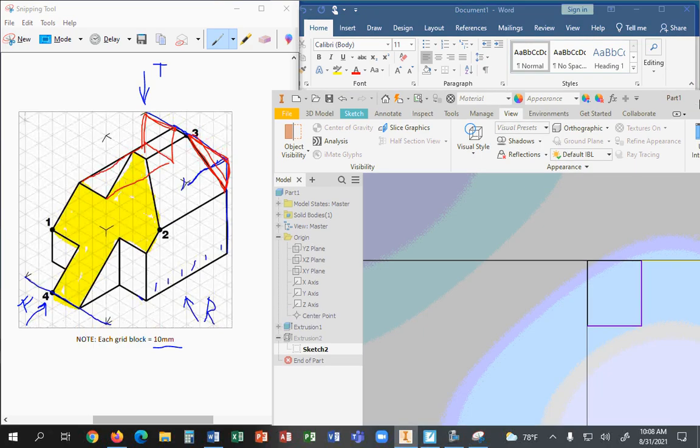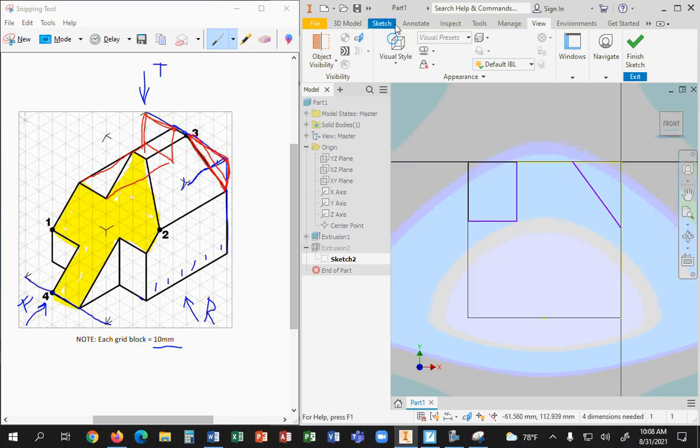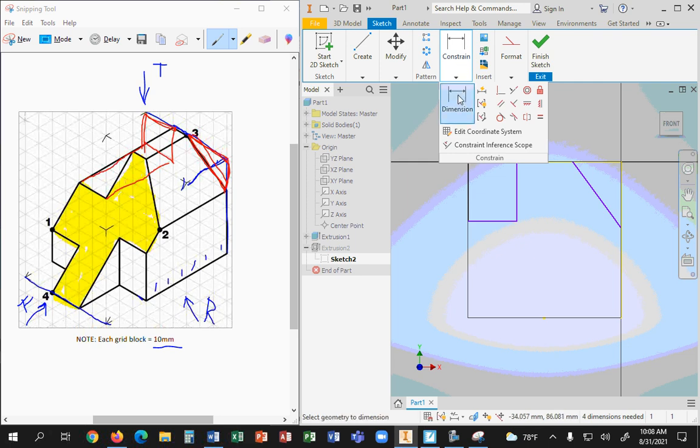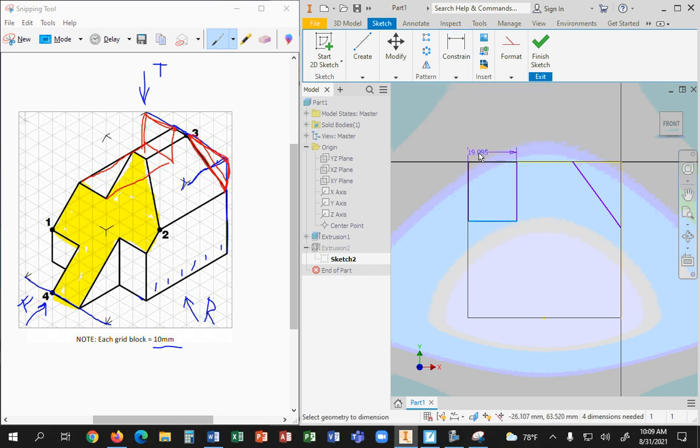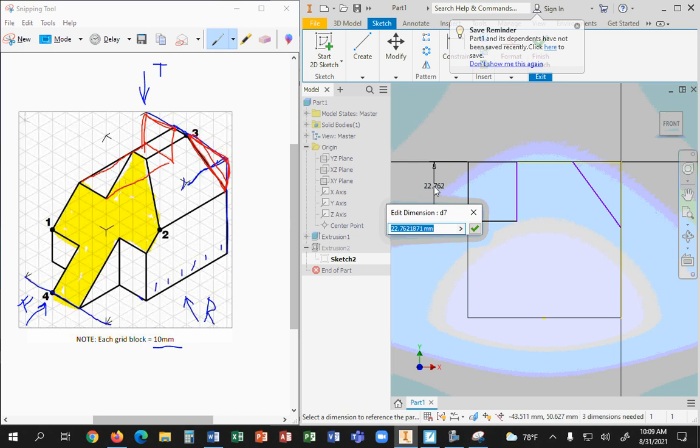Now in this view, I can go ahead and apply the dimensions I need to apply, the dimensional constraints that are important. Now notice I picked the midpoint. No, I don't want midpoint. So I just hit escape, go back to dimension. I want to pick object to object. Go out here. And what size square is that? 20? And I hit that.